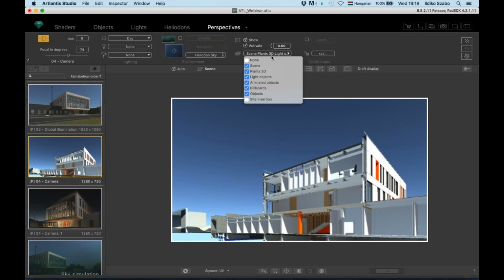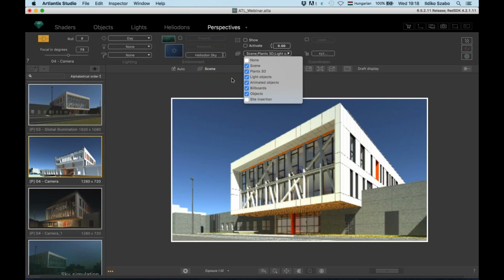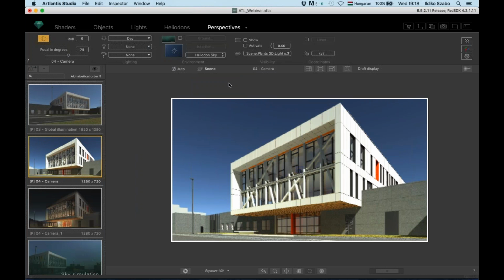And of course the layers. The layers are meant to organize objects, and all these objects can be turned visible or not visible, because the layer was set visible or not visible, which allows us to do variations. So just imagine an interior with different furnishings. Using these layers in the frame of the same file, I can very quickly reorganize this furnishing and generate multiple presentations around it. Okay,